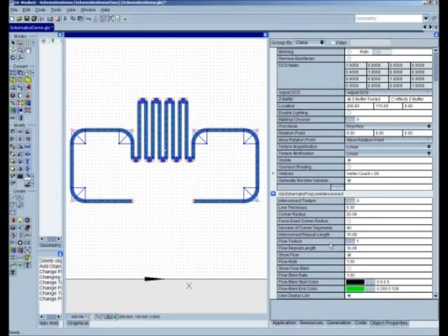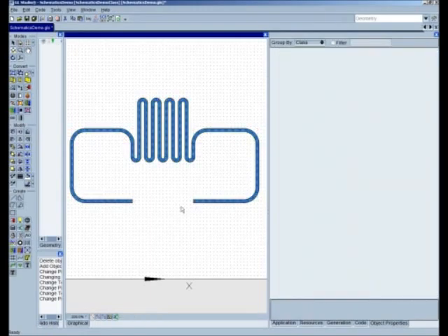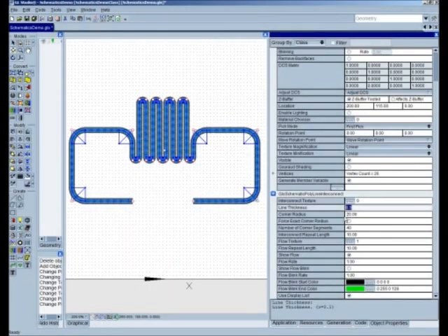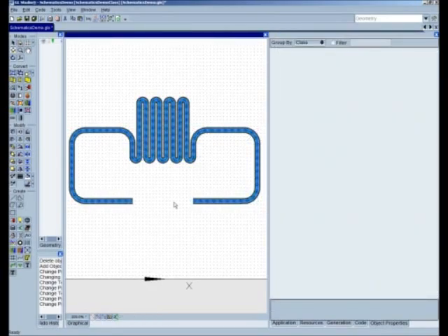So we've applied the flow texture, and we can see that in the editor, the texture is actually animating. This is actually what's so great about the Animated Schematics plugin. This isn't something where we have to draw it up and then compile it and then run it and then hope it looks the way we want it to. With this particular plugin, we've built up the whole thing, and we can see it running inside the editor so that we can verify the look and feel and make any changes. For example, if I think that's too thin, I can go ahead and adjust the line thickness up to 8, for instance. And we see the effect inside the editor in real time.